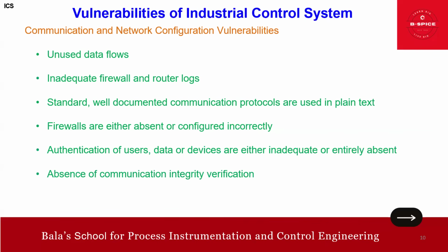See, friends, most industrial protocols lack a built-in integrity checker, potentially allowing adversaries to tamper with the communication without detection. To ensure integrity, ICS systems can implement lower layer protocols like IPsec, which provide data integrity protection. So the point is we should implement lower layer protocols for protecting the data and integrity.